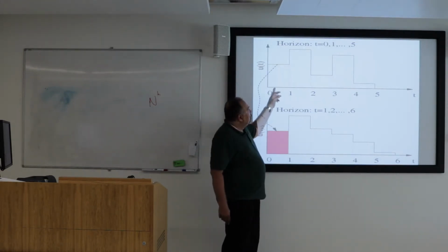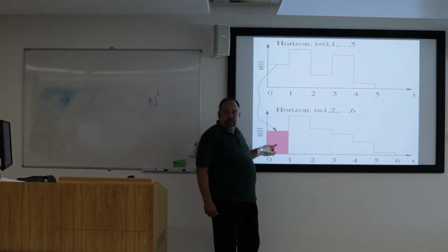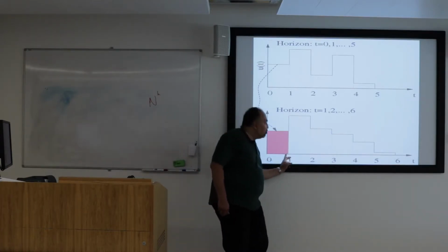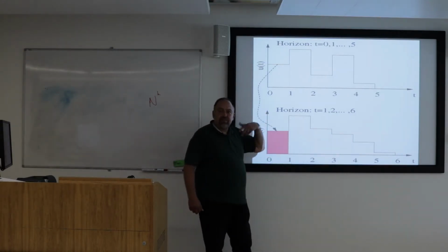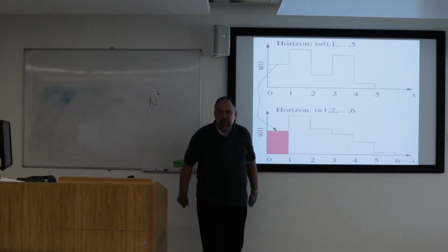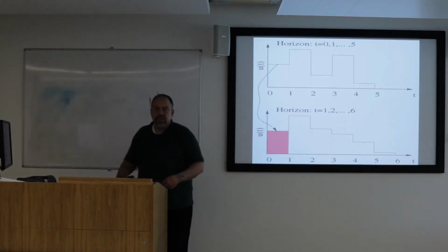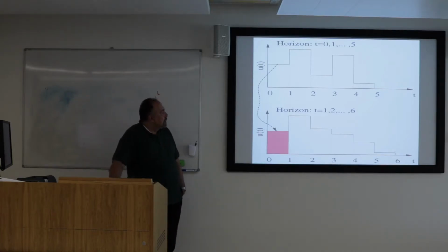The moment you have an optimal solution, you take the control action for the first step and you implement it in the actual process, and while this is running, you remeasure your process and you run another optimization up to step 6, and then you take the first step that's available, you apply it to your process, and you move on like this. So with a longer horizon, you're trying to capture also the stability of the process or to ensure it. So this is how model predictive control works.